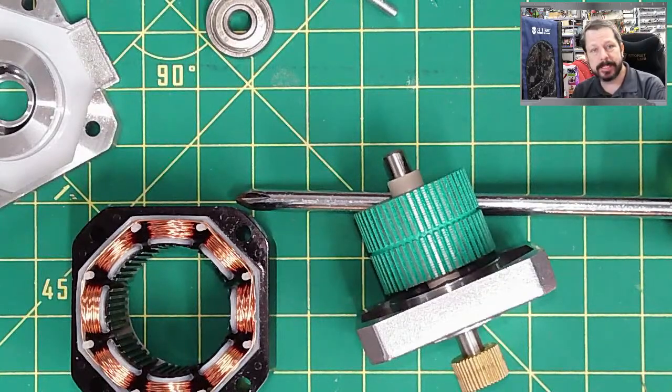It was way more interesting when you had 8-bit boards in the printers, because you could take that existing board, leave it in your printer, put a Raspberry Pi in front of it, and suddenly you have an entire PC, the Raspberry Pi, doing all of the processing. All your board had to do was send stepper motor commands, which it could do really fast. It just couldn't do the processing of what commands to send. So it made a big difference in those kinds of setups. Now that most printers have 32-bit boards, it doesn't make that big a difference. You still have more power in the Raspberry Pi than you do on the printer's board.